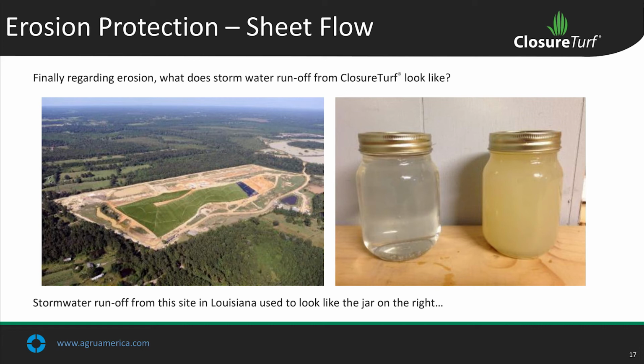The storm only caused a 1% sand loss over the entire 23 acres of the cap, mostly around the perimeter ditch here. It took 2 guys 1 week to restore it all back in place. So this is a very durable closure system with respect to intense rainfall.